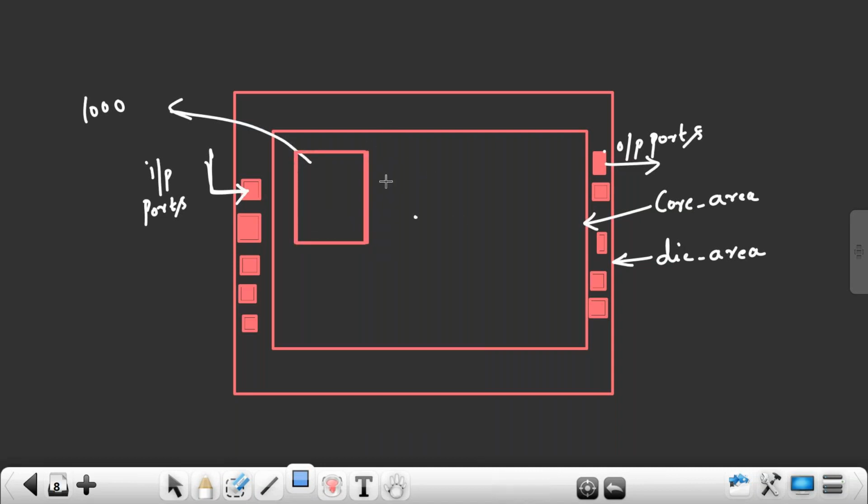Like that I have only 40 macros. Now what is my cell count? 40 macros. Inside that macro I am not worrying. Why? Because it's already optimized. The vendor tells that I have already done the connections. I have implemented all the layout of the standard cells inside the macro. He is already giving me the LEF file. Why do I have to worry about what is present inside? Directly take it and use it, right?